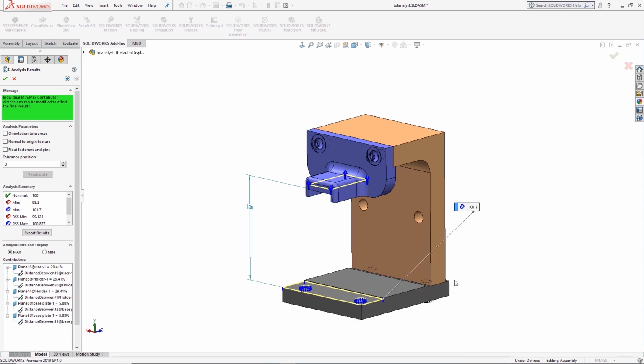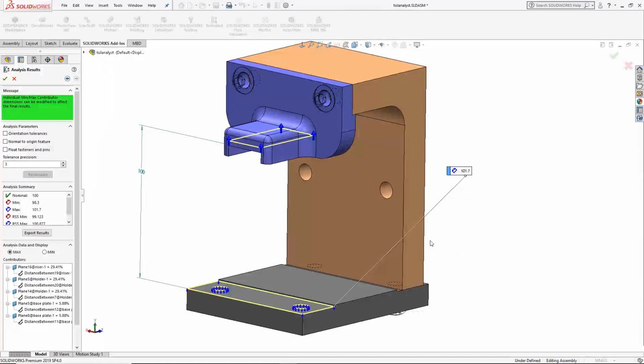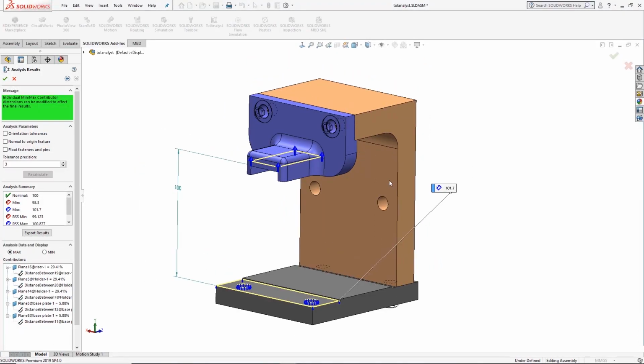Now, what we can do is, well, for starters, we could actually change the nominal size of our components. Just make them either a little bit smaller or a little bit wider, depending which direction we wanted to go. We can also change what tolerance those values are using, so we could potentially manufacture it slightly differently, maybe use a different tool. Now in this case, let's go and change the tolerance of that top dimension here.